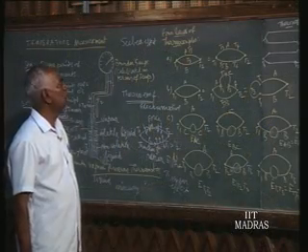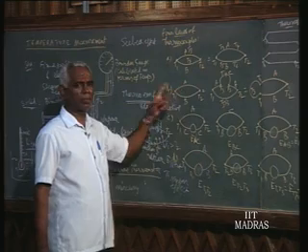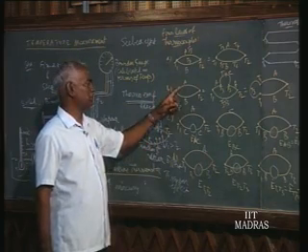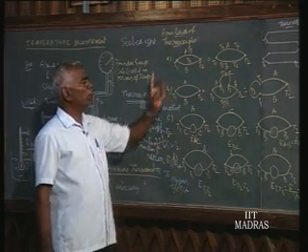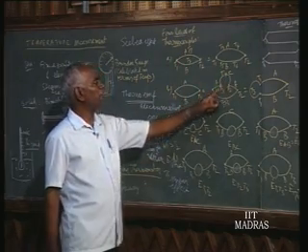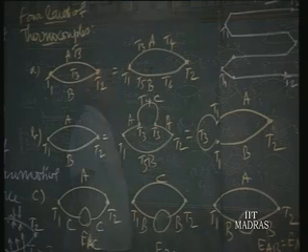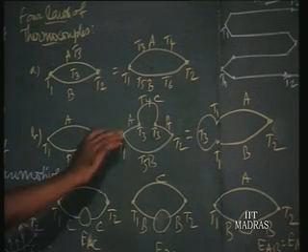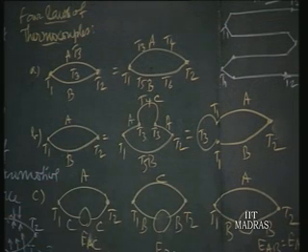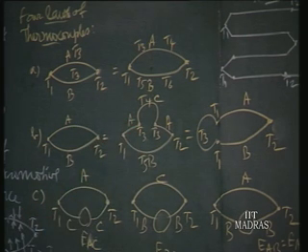So that is the first law of thermocouples. Second law states we can bring a third element, because thermocouple circuit is made up of 2 elements, homogeneous element A and B. Now I am bringing a third element C, cutting the material A at these 2 points and connecting the third member C. Now here the voltage developed will not be affected if, that is important, if the 2 new junctions are at the same temperature.